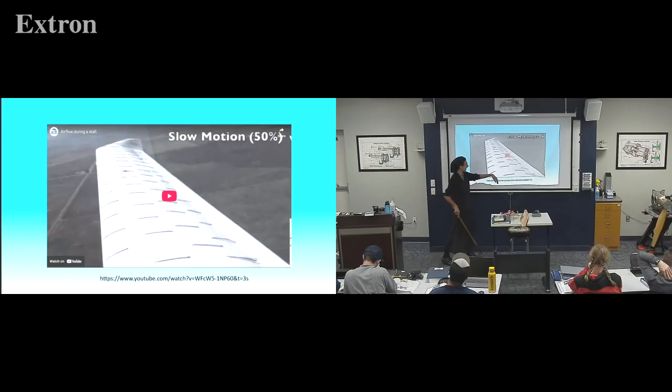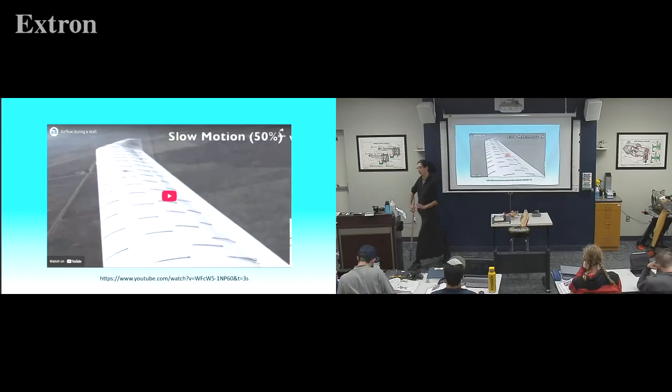And you'll see as they bring the nose up, but they stay at the same altitude, you will see these strings wiggle as the air becomes turbulent. And these are kind of always wiggling because our transition area is about in here somewhere in normal flight. But these will wiggle, and these will wiggle, and these will wiggle, and then they recover, thankfully. So here we go.